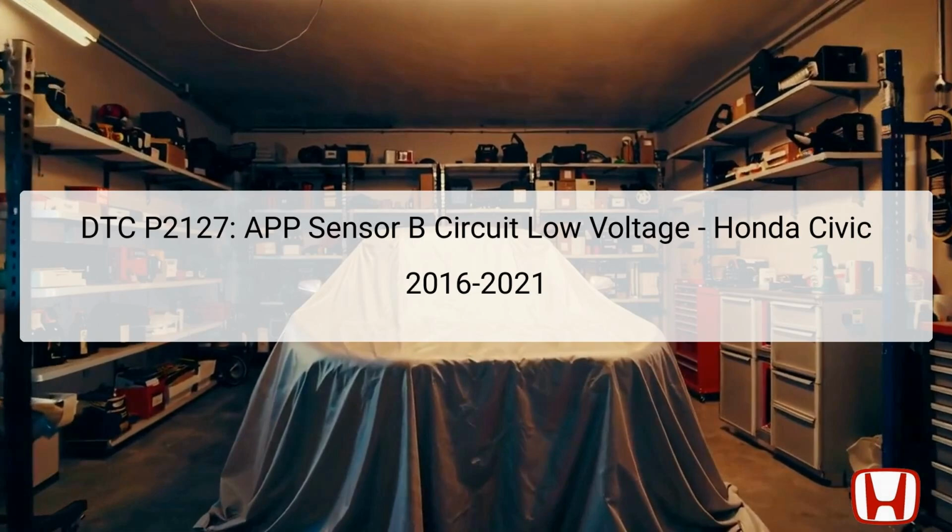DTC P2127 is a diagnostic trouble code that indicates a low voltage condition in the APP (Accelerator Pedal Position Sensor) B circuit, specifically the TP (Throttle Position Sensor) E. This code is part of the PGM-FI programmed fuel injection system in the Honda Civic models ranging from 2016 to 2021. When the engine control module, ECM, detects that the voltage from APP sensor B is below the expected threshold,